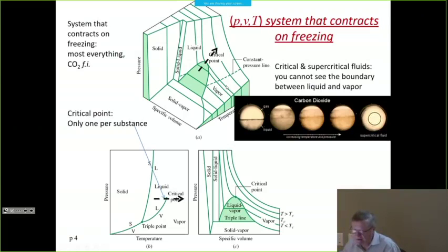So this is the state of the liquid. Liquid, gas, you don't know what it is. It's a mixture of both here, whereas this is clearly in the vapor dome where we are here. It does actually matter because we are going to use supercritical fluids. We will use supercritical water in steam turbines, and some of the refrigeration systems use supercritical carbon dioxide like what I showed here.